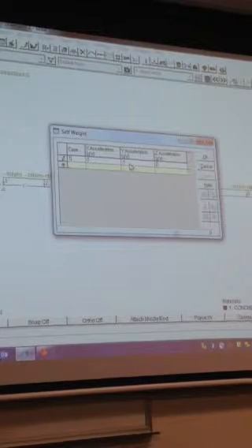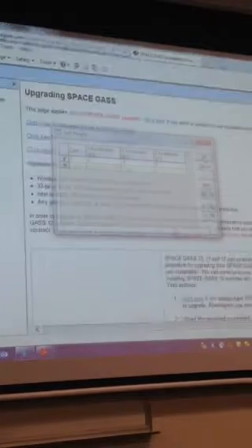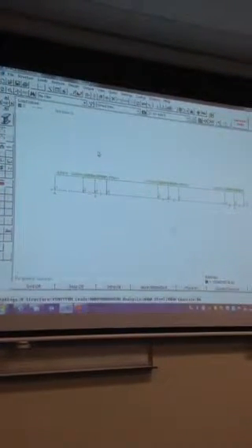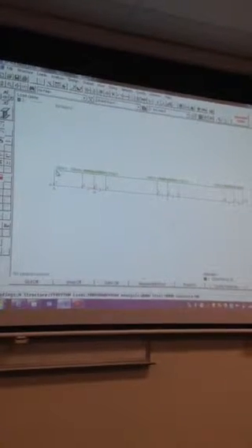So we just want -1, so minus being downwards again. We can OK that. And under the load case, it says SW. So now we're telling the computer, or the computer's telling us, it's included the self-weight in that load case. All right? Whereas if we go to load case 2, it doesn't say it there because we've only included it once.